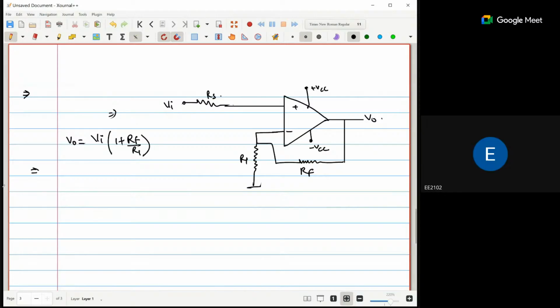But the problem with this operational amplifier working is that if we implement this circuit, we require two supply voltages. If my VCC is 5 volt, I have to create a plus 5 volt as well as a minus 5 volt. And for an independent circuit, what should I do? There we have a 220 volt supply.